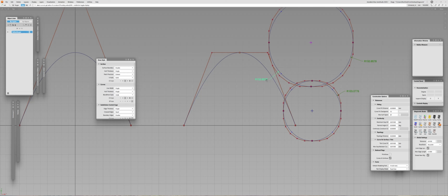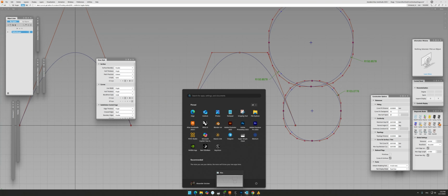And that's where the power of the NURBS is actually visible. It's in the conics. In all other aspects, regular B-splines will be just fine, or at least when we're talking about curve creation. But of course, underneath, mathematically speaking, you are really operating with NURBS, not with B-splines. It's just that the value of W is 1. So let's go back to my scribbles.